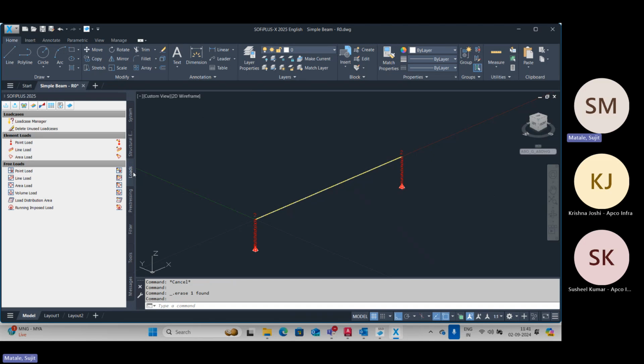So that is very clear to you now. When I say load types, it is clear why it is required, right? So in order to perform combinations, you need to work with the action. This is the idea. Or the user can also work with each load case into the factor and all. Okay, that's why we need to specify each load case to an action.